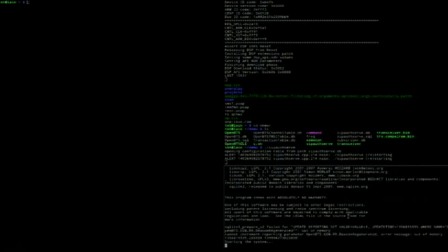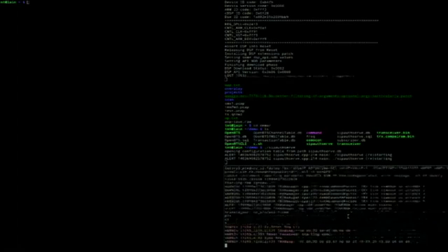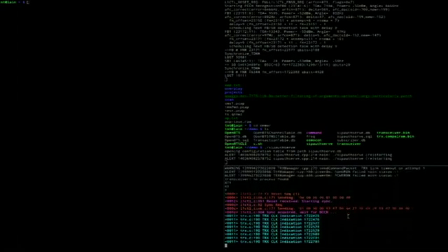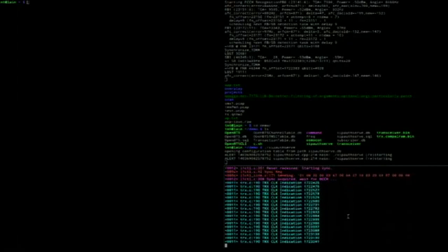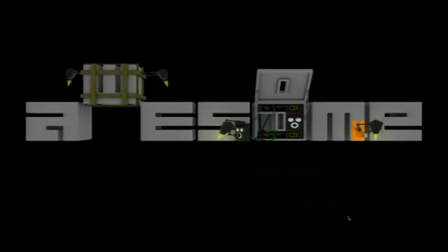Then you just start OpenBTS. OpenBTS itself will start the transceiver application in a moment, and the phone is synchronizing to the commercial network. Then OpenBTS starts to transmit bursts, and this is hopefully broadcasting a BCCH now. If we look at Wireshark,